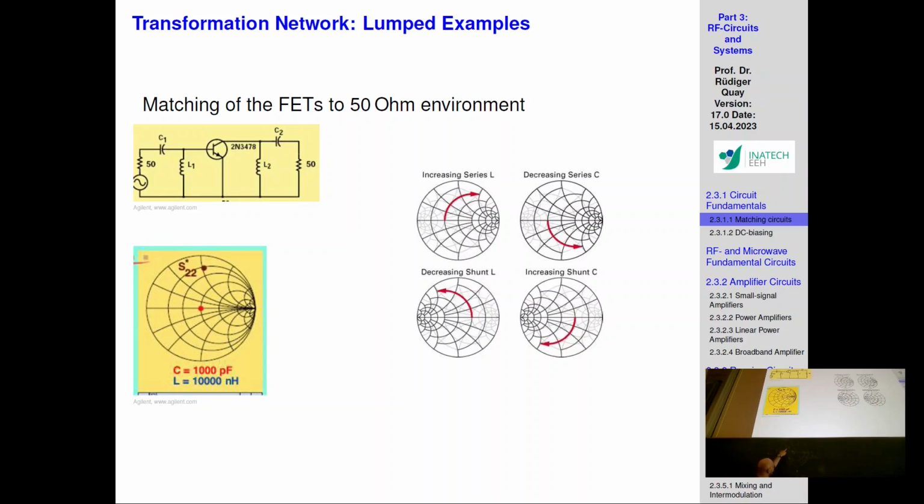Well, how do you reach this point from this point? Well, you can see, I need to do a matching network. What is a matching network? A matching network is a series of LCs. So there's a series L, and a parallel C, and then a series L, and a parallel C. And how you do these parallel Cs, if you do them as stubs or as MIM caps or whatever, and how you do these Ls, that is your decision. It's basically a filter.